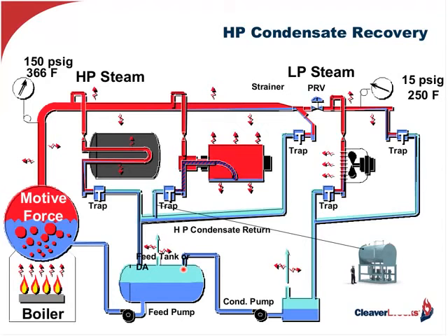So let's say we can't do that. What else can we do? Well, I'll tell you what we can do. We can take that hot condensate, maybe at 80 or 90 pounds, and if our line is properly sized, take it back to a high-pressure condensate receiver, which has been designed for this particular application. Now, maybe we have to use a pump trap to get it back, but the juice may indeed be worth the squeeze.